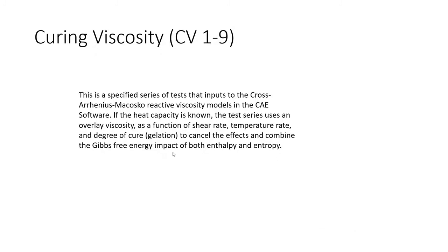And we could cure the silicone just through entropy effects, through mixing at extremely high shear rates, numbers that were probably in the range of 200,000 to 300,000 reciprocal seconds. And we were able to cure it in less than 5 seconds without even heating the mold. That's how important entropy is.